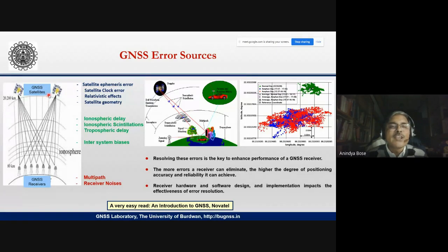They have got their relativistic effects. So the satellite clock would have some very small error, maybe of the order of a few nanoseconds or less. But when we are talking about millimeter level accuracy, I'm giving a second problem to the students: if there is a measurement error of 1 nanosecond, what would be the distance between the two measurements? Order of 1 nanosecond distance difference. So what would be the difference between their positions? Right. So you will find out yourself.